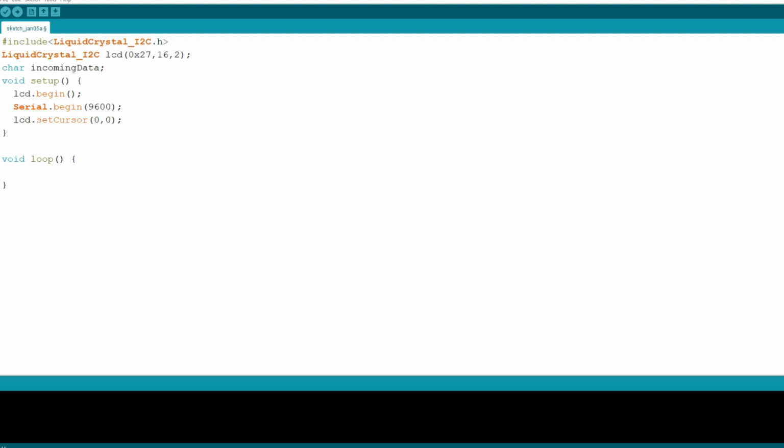Now what we have to do is create a condition here. With this condition we will learn whether a signal is coming to our Arduino board. So let's write here if, open and close parentheses, create curly brackets and close the curly brackets. Then let's move inside of our parentheses and write Serial.available() greater than 0. Our logic here will be as follows. If data comes to our Arduino board, the condition here will be true.